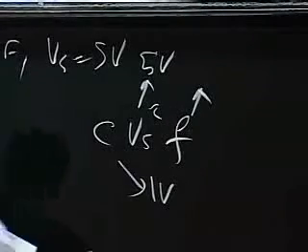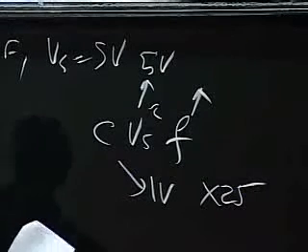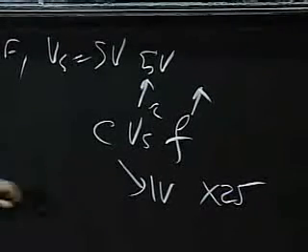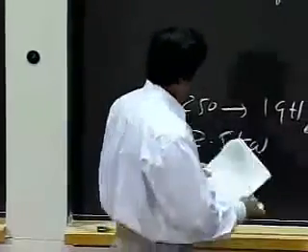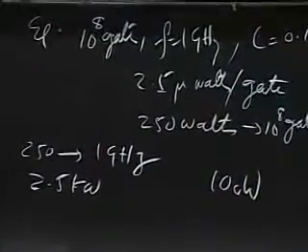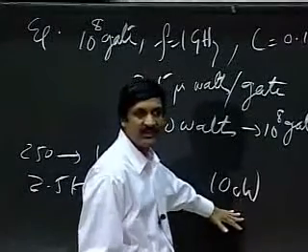The moment you do that, you get a 25x reduction in power. So going from 2.5 kilowatts, you would now come down to something on the order of 100 watts, which is much more reasonable. Again, all else being equal, the capacitance of devices also changes as you go to smaller and smaller devices. Now, 100 watts is still pretty high, and not good enough for mobile computers. So there are many other tricks that people use to get even lower power.